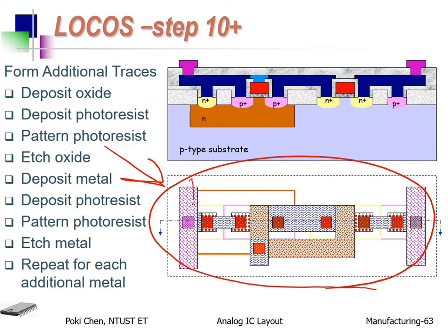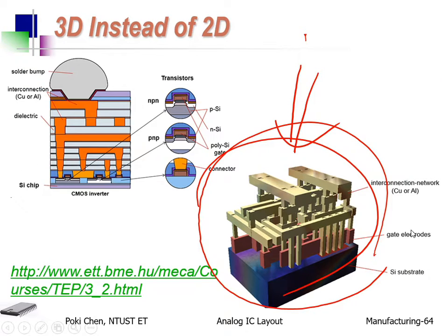Something like this, the metal 2, the metal 1, but because they are at different layers, right? Even if you have such kind of overlapping layout, they are not connected. You need what? You need vias. Keep this in mind. You need to do it by yourself. And the other issue is you can see from this, for example, the top metal to the bottom metal, because there are quite many layers in between. Don't expect there is a via from the top all the way to the bottom.